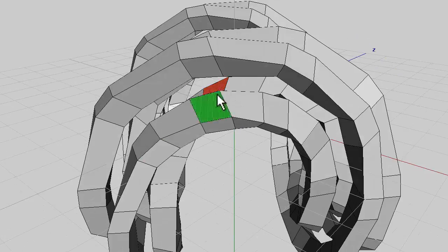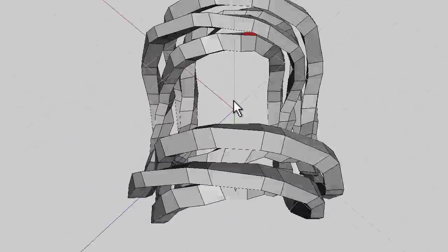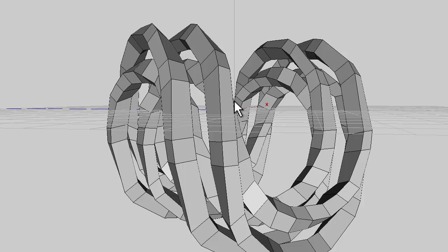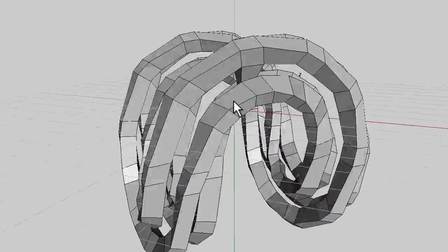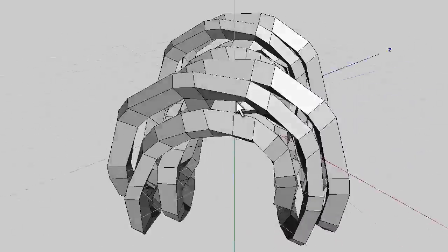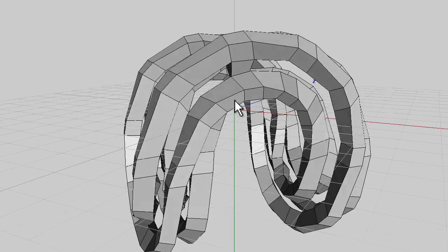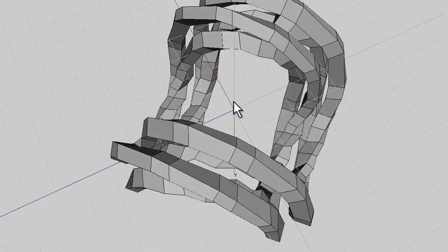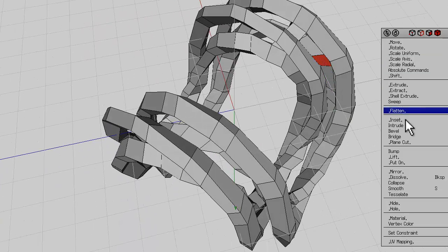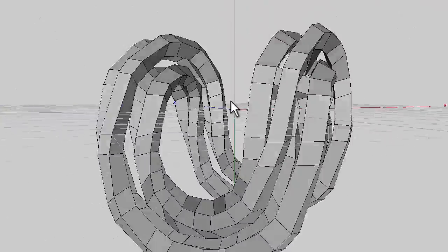So that face there, for example, turn the thing round, can't see where it's selected very easily, so you have to sort of remember and work it out. We'll connect to that face there, so you just highlight those 2 and bridge, and that's bridge those 2 together. You see that? Now the next thing then is opposite ones, so it's that one there and that one needs bridging. Try and work it out by turning this round, it gets a bit confusing, to that one there. You can always go back by controlling Z, and Wings 3D is far less likely to crash.